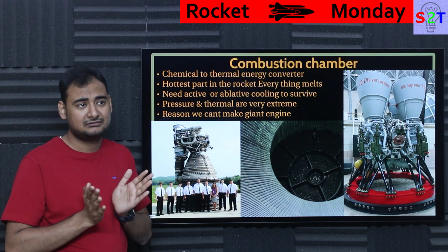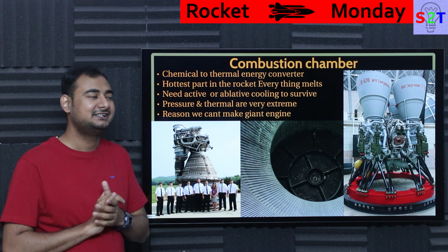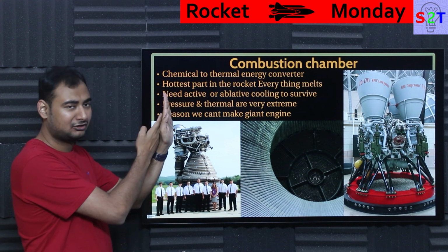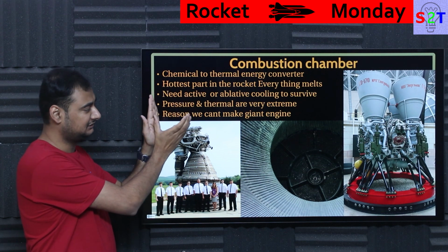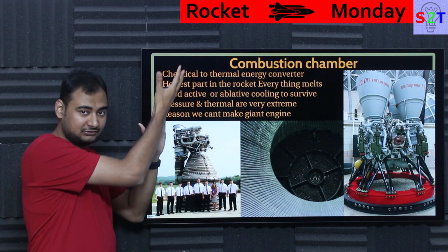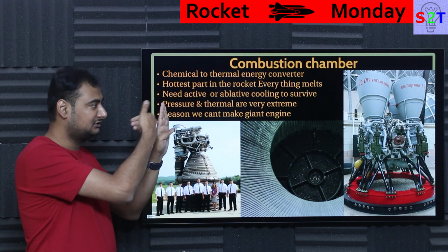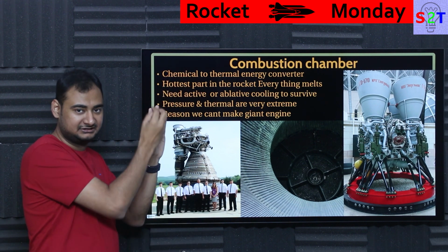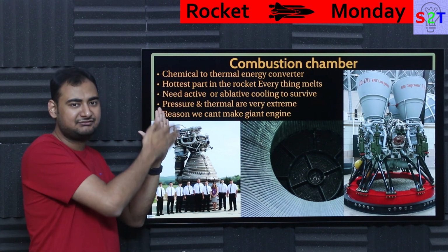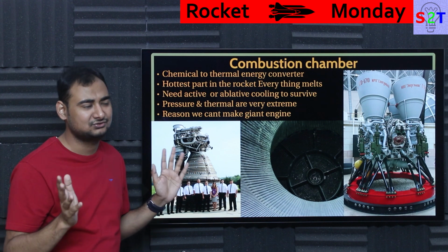Well, yes, it burns off, it changes your geometry while in flight, but it does have the benefit that it's taking heat away. Meaning if you have your chamber wall, this shall not melt, you put a graphite layer, a very thick graphite layer. Now graphite burns, but again, if it's burning, it's outgassing, it's literally going away, so your heat is not penetrating through it, because the thing that's supposed to absorb the heat is getting destroyed by it and getting exhausted, you don't have to worry about it. Again, it's supposed to last for around 2 to 3 minutes.